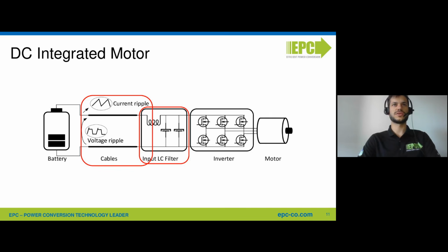So inductors, common mode chokes, or big electrolytic capacitors. So it's typical to use an EMI filter, and that has some limitation due to the switching frequency.